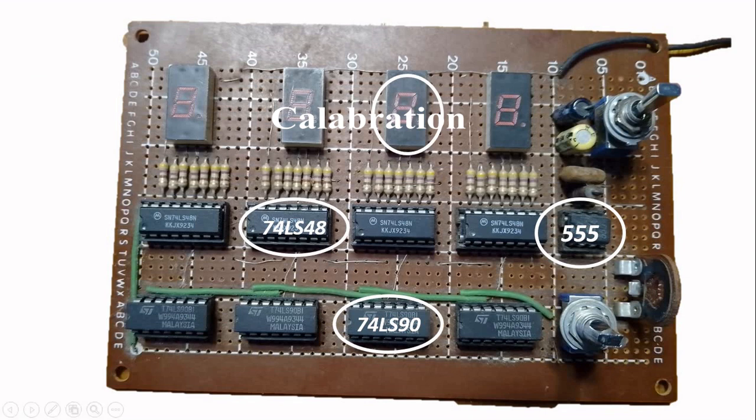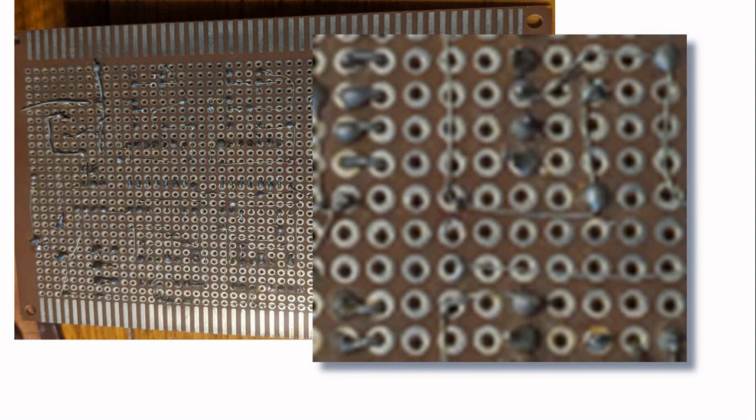But how did I test the circuit? I built a very simple program in the PLC which says 10 seconds or 20 seconds, and then I counted how many counts went through my relay in those 20 seconds. Then I can divide it by 20, and I know exactly how many pulses come in 1 second. In this particular case, which you will see in a video when it is running, it's about 1250 pulses per second. As you can see from the back, it's a pre-drilled card.